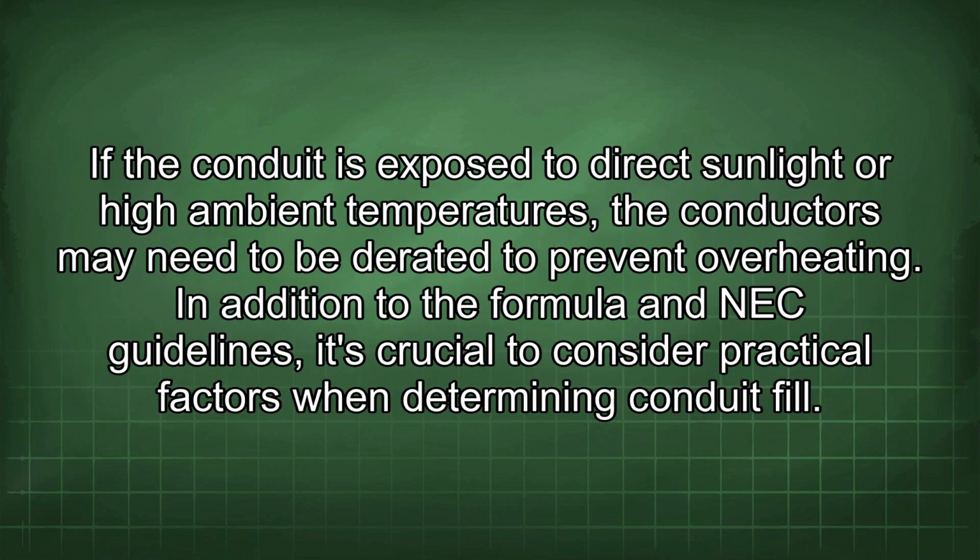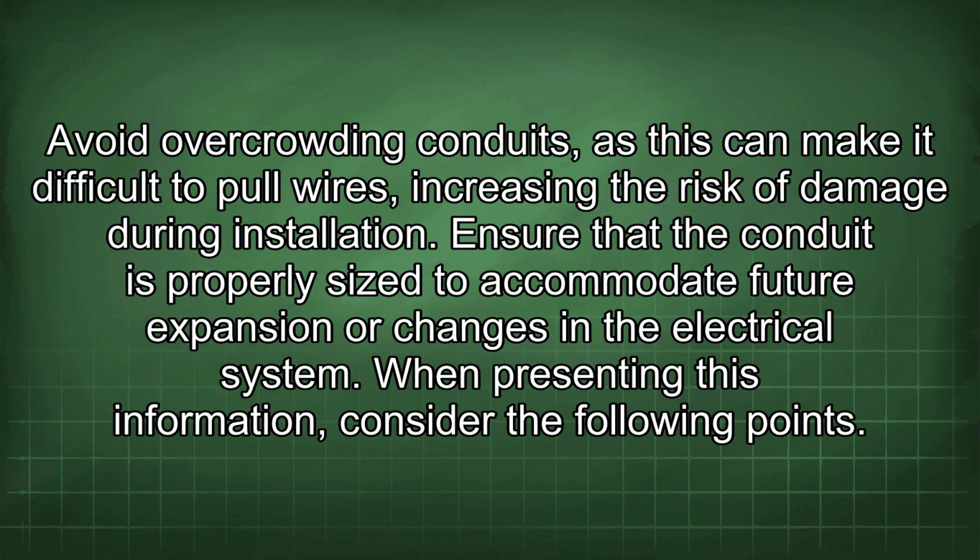If the conduit is exposed to direct sunlight or high ambient temperatures, the conductors may need to be derated to prevent overheating. In addition to the formula and NEC guidelines, it's crucial to consider practical factors when determining conduit fill. Avoid overcrowding conduits, as this can make it difficult to pull wires, increasing the risk of damage during installation. Ensure that the conduit is properly sized to accommodate future expansion or changes in the electrical system.